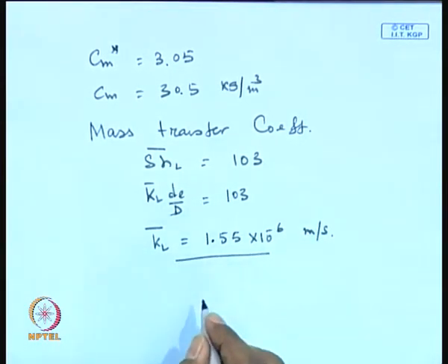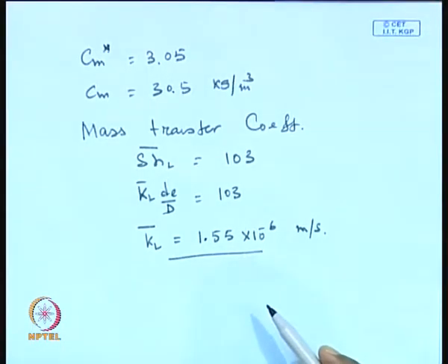meter per second. So, this problem gives a demonstration how we are going to use a more accurate method that we have discussed earlier, that is a 2-dimensional approach in terms of length average Sherwood number and length average permeate flux and length average membrane surface concentration, all these quantities are length averaged. So, in this process also, although we have used a 2-dimensional model, we are not solving any ordinary differential equations or partial differential equations. Our equations will be basically boiling down to the solution of 2 simultaneous algebraic equations, exactly like the film theory equations, but the only formulation is changed.